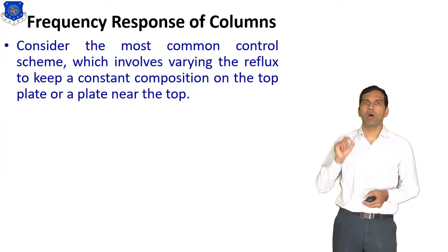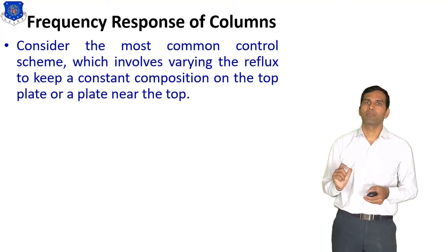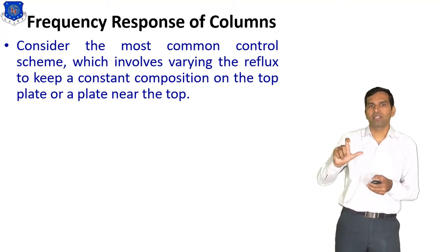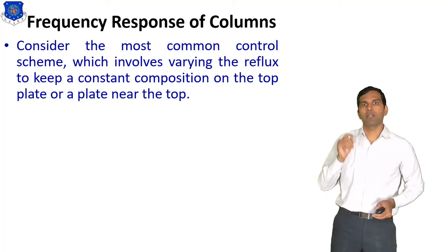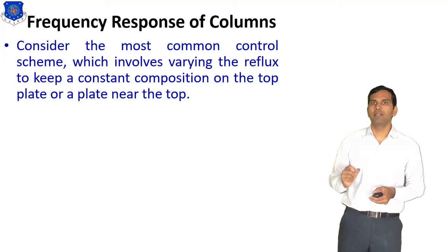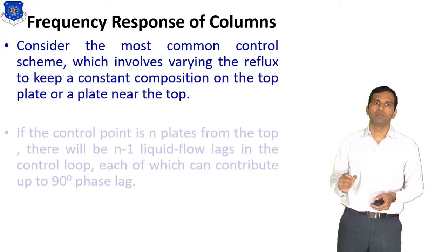Consider the most common control scheme, which involves varying the reflux to keep a constant composition on the top plate or a plate near the top.